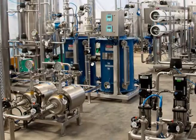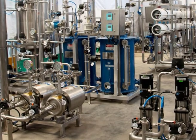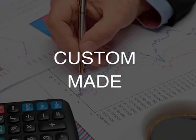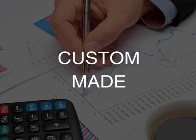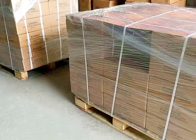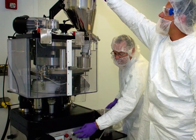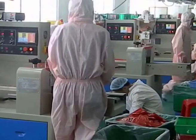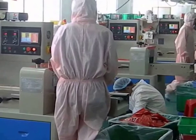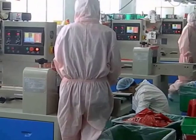The material ready for further processing should be immediately weighed and labeled accordingly, and the weight should be recorded in the batch document. All entries in the BMR should be done immediately. In-process goods should be stored only in the area provided. Standard operating and cleaning procedures should be strictly followed. Any adverse incidents, spillage or deviation observed should be immediately informed to the supervisors. All the safety instructions should be strictly followed.